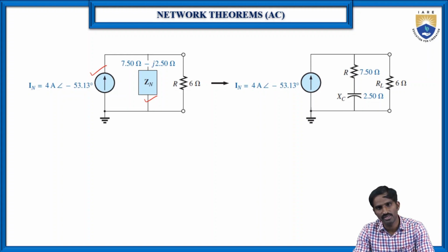and these three components are connected in series. But when coming to Norton's theorem, of course here also we will have three components, but the difference is, instead of V Thevenin's, here we have I Norton's, because there it is the Thevenin's voltage, here it is the Norton's current. The Thevenin's voltage is also called the open circuit voltage, and the Norton's current is also called the short circuit current. Because we are replacing the load with an open circuit, and in between those two terminals we find the voltage, that's why it is called the open circuit voltage or the Thevenin's voltage.